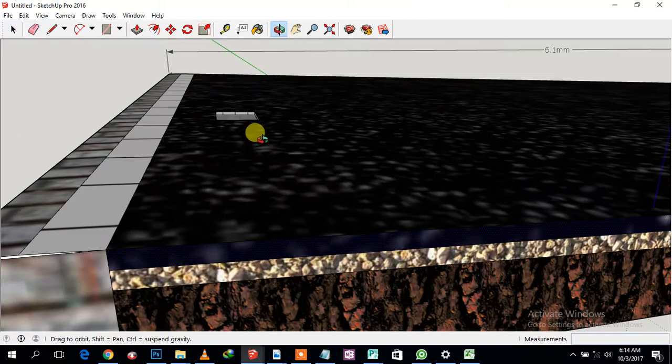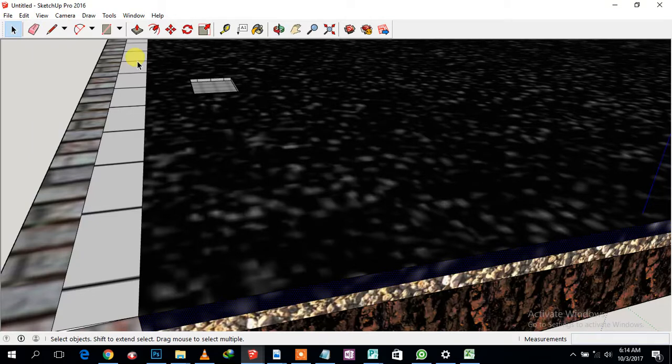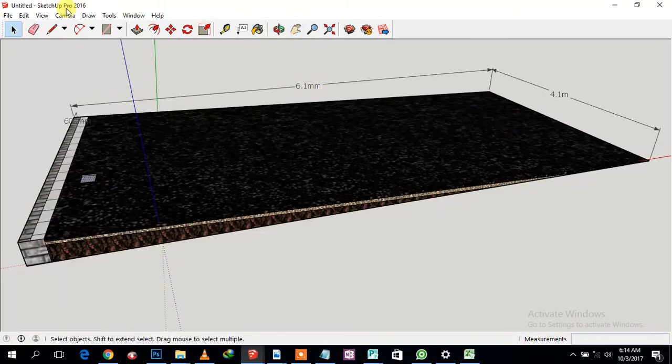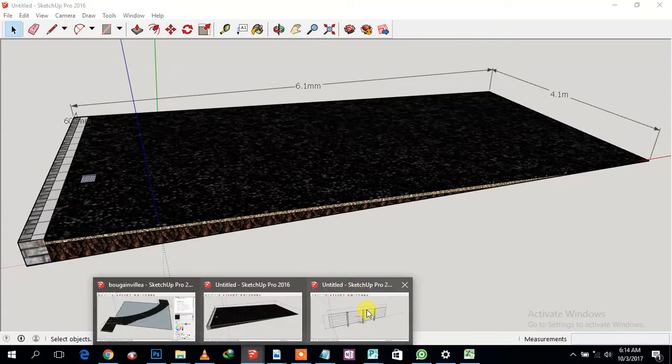And of course, we're going to put a drain grid as you requested, that is going to capture all the storm water runoff, because there's going to be a lot of water probably coming from the driveway and this new parking platform, so it's going to get captured in this drain grid. And we're going to put a pipe that is going to join to the existing stormwater system. And then my other presentation is the precast fence.